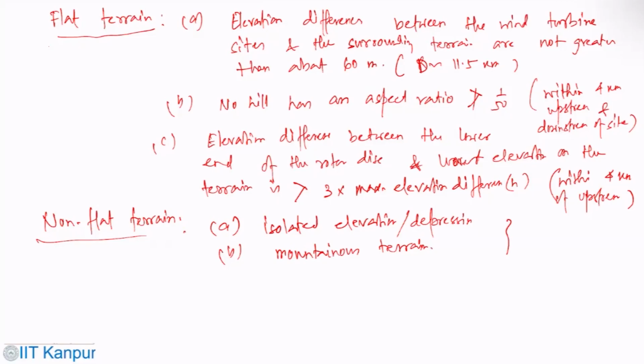Obviously, the distinction between these two is made with comparison to the planetary boundary layer, which is assumed to be about 1 kilometer. So one important point to be made here is that information on wind direction should be considered when defining the terrain classification.